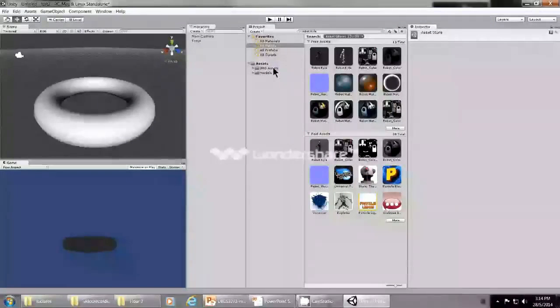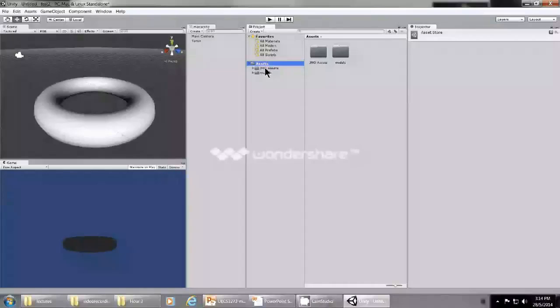So now you can see in your assets pane, we've got a new folder called GMO Assets, and this represents the robot Carl that we've just imported. If you are not able to import this because you are behind a firewall or proxy, or you don't have a good broadband connection, inside this lecture folder I've also included another folder containing a project that contains this pre-imported asset. So you can open that project in case you didn't manage to download the assets from the Unity Online Store.